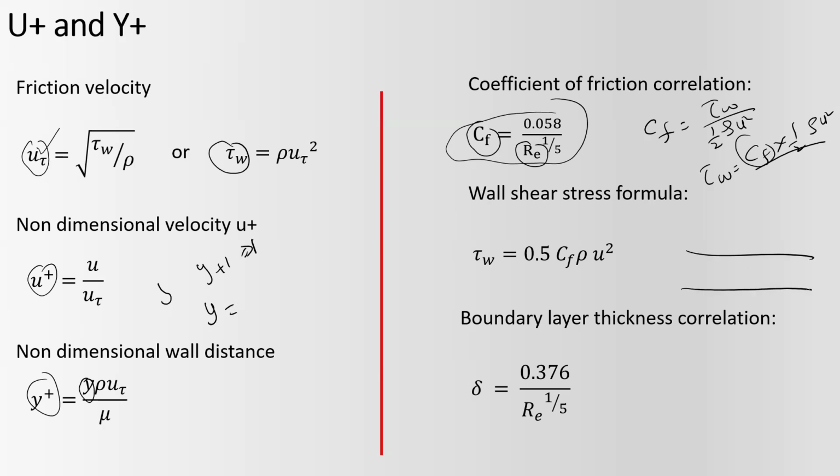So you have to solve for the Y. This is the first cell height. So we have the mesh like this. In the control volume, the first cell height is not this one, but this is over here, up to the first node from the wall. So you have to find out the Y for this value. Y is in the normal direction. So I can solve for the Y value: Y will be equal to Y plus into viscosity divided by density and the friction velocity.